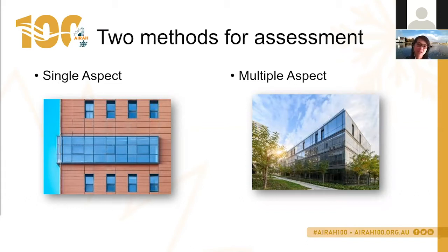It's the same sort of concept with the wall glazing requirements for both system U value and solar admittance. You can either try to comply on the north, east, west and south aspects separately, or if you find that one aspect doesn't comply, you can look at it as a whole that is area weighted to see if you comply.